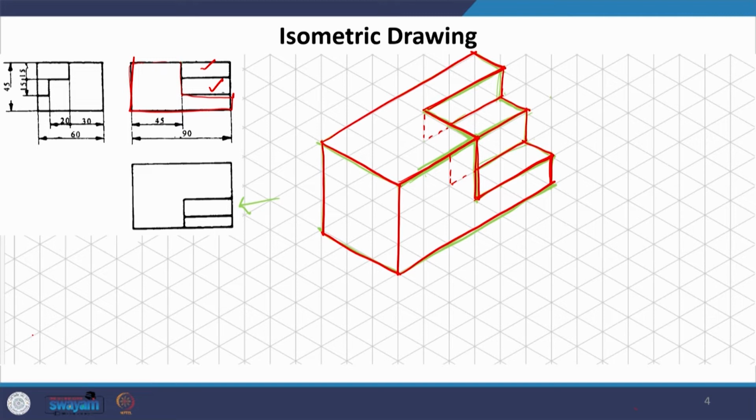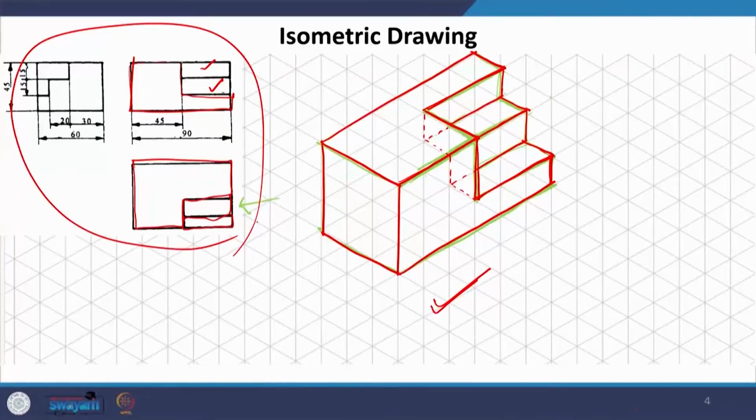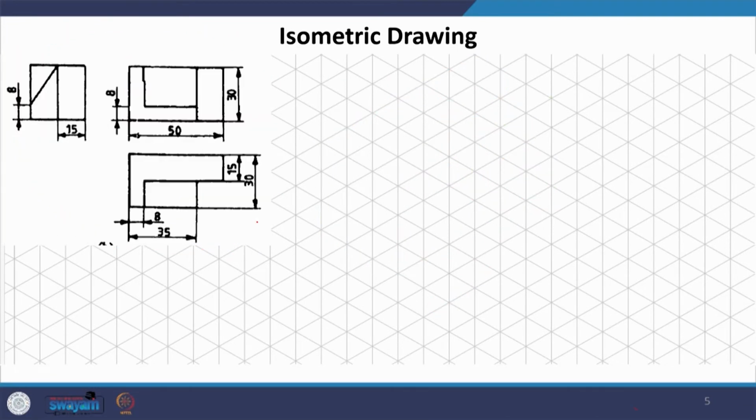For the plan, we saw this, a continuous surface, which is what we are seeing here. Then we have one box here, which is the box here, which is this, and then another one here, which is this. I have skewed the dimensions a little bit, but if you actually see, you will get this if you are drawing absolute dimensions which are given. So, which means that this isometric drawing which we have drawn out of this orthographic drawing is absolutely correct.